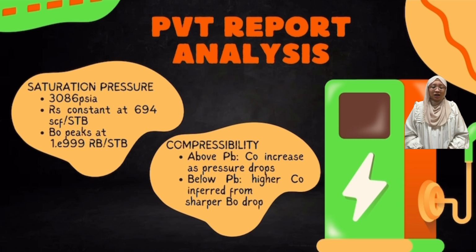After this, RS declines and BO decreases, the classic indicators that gas is separating from the oil. Therefore, we identify 3086 psia as the saturation pressure. This value aligns with results from both the correlation and plugin, confirming its accuracy.